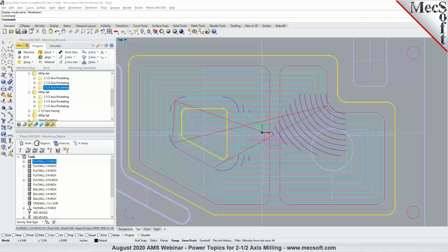your machining tolerance. But if you are machining an arc, it's possible that our arc fitting will give you an exact arc. But in some other cases, let's say you're machining a NURBS curve, and we fit an arc to the resulting toolpath, that might result in a little bit of an error. So you've got to be a little bit careful about what we call tolerance stacking, because you have a machining tolerance. On top of that, you have the arc fitting tolerance. So I hope that makes sense. Thank you.